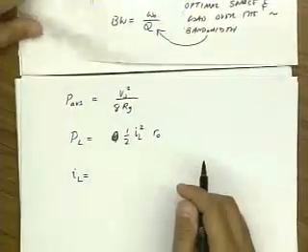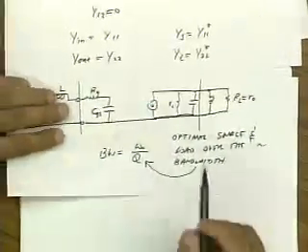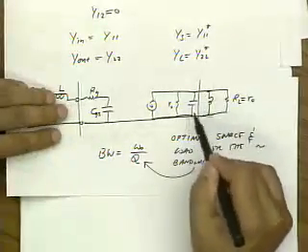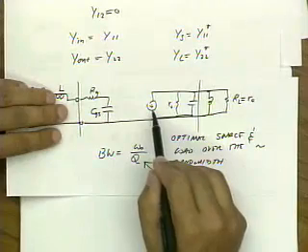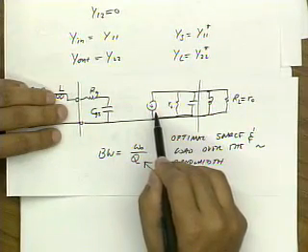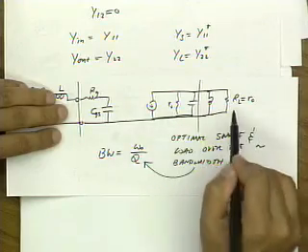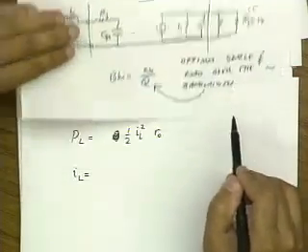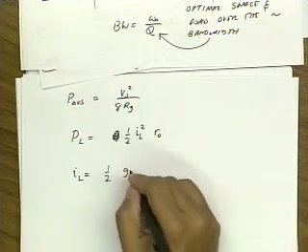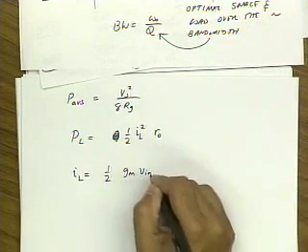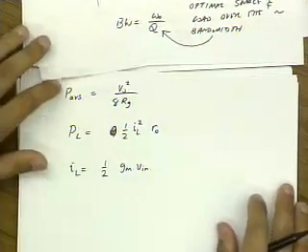Well, in resonance, there's a circulating current flowing between the L and the C, and so the current from this gm generator all flows into the real resistances at resonance. So half of it flows here, half of it flows here. So we can say that the output current is 1/2 gm times V in. Okay? So now we need to find V in.